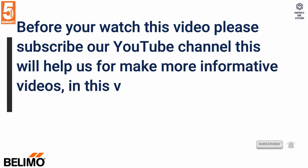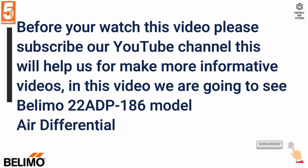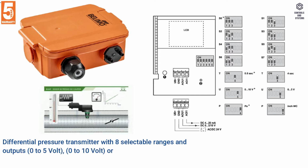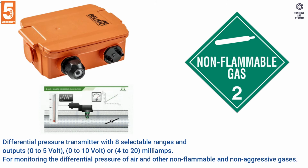In this video we are going to see the Belimo 22AD-186 model Air Differential Pressure Sensor complete technical data. Differential pressure transmitter with 8 selectable ranges and outputs 0 to 5 volt, 0 to 10 volt or 4 to 20 milliamps. For monitoring the differential pressure of air and other non-flammable and non-aggressive gases.